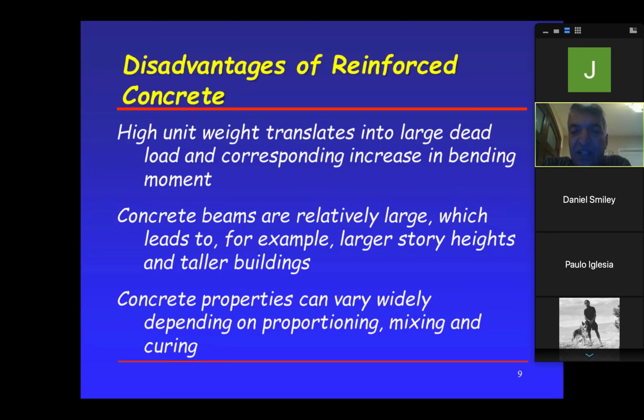Second, like he mentioned, is the cracking. Again, if the water is evaporating, that means the volume of the concrete is being lost to evaporation. And what happens when the volume is decreased? The material is going to move. It's going to shrink as a result of that loss. And when something shrinks, it's going to crack. Very good comment. Thank you.